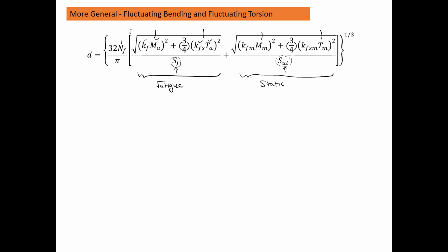Okay, so Kf is equal to 1 plus Q for bending. So now we're talking about bending, so I'll need to go to the bending charts and find that notch sensitivity times Kt, the static for bending for that structure that you're analyzing, minus 1, so you'll find your Kf, and usually this is equal to Kf mean, so the mean value for the stress concentration factor in most cases. But it can be different if you calculate a different value for Q.